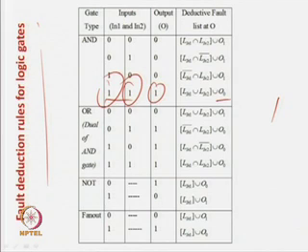So, this stuck-at-0 at the output will be detectable, and whatever list is here and whatever list is here. So, it is L1 union L2. Both of the fault lists will be propagated. So, this is for the AND gate.